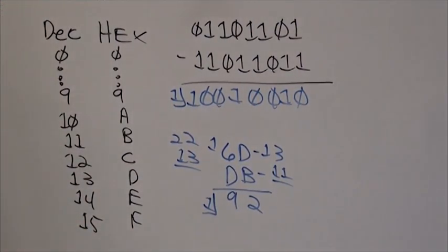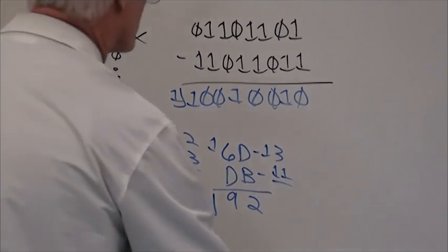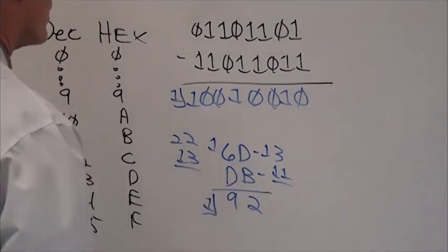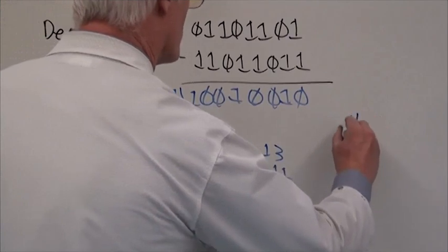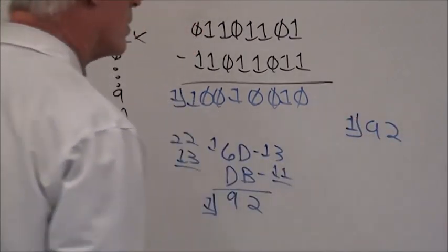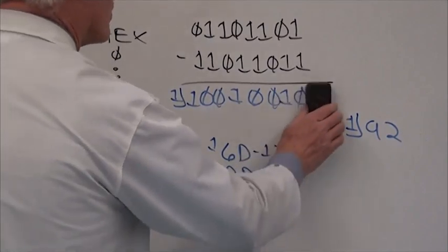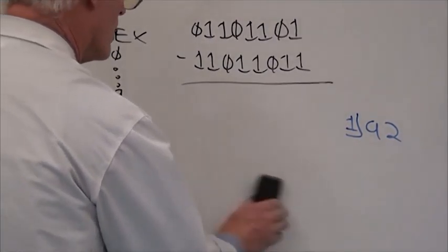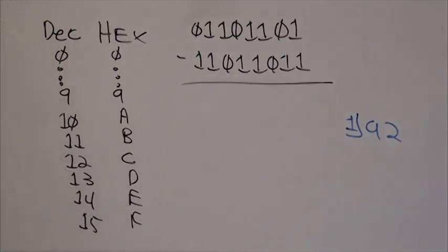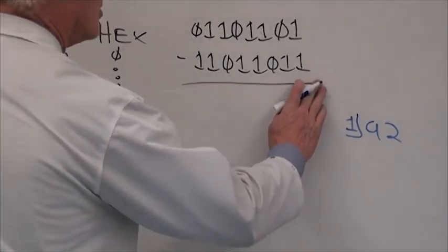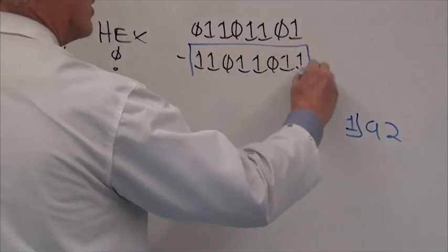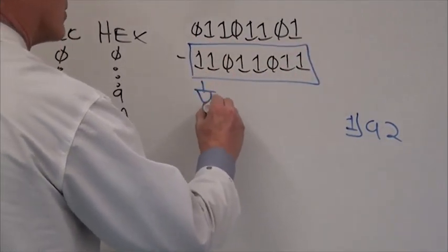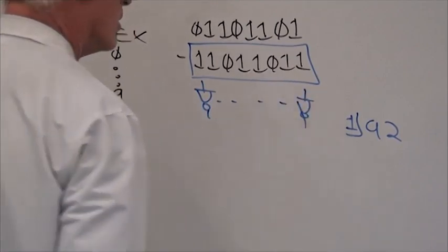However, when you're taking DGS, they will show you the 2's complement arithmetic, which will get the same answer, but it's going to take a lot of steps. Let me show you what the DGS teacher is going to do. So our answer, let's just write it over here so we remember, is 1 in hex, 9, 2. Here's what it does, because digital circuitry cannot subtract directly. It uses a trick. Here's what the digital teacher will tell you: you take this number and you put it through 8 inverters, because digital circuitry has inverters.